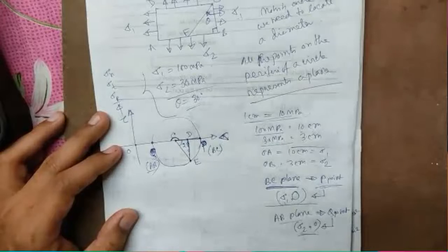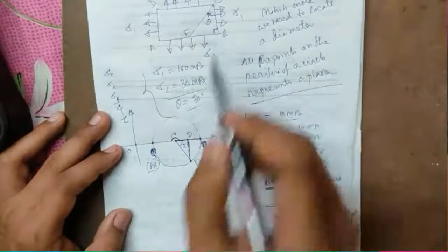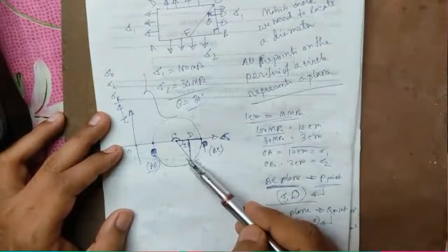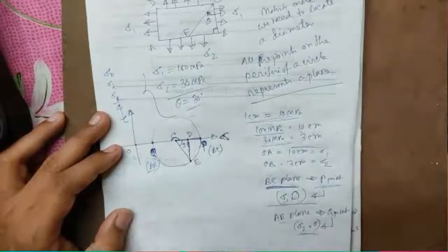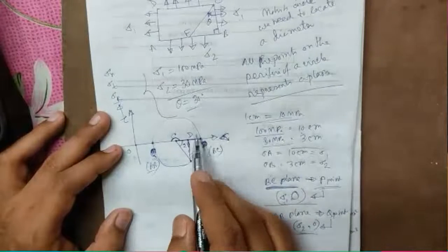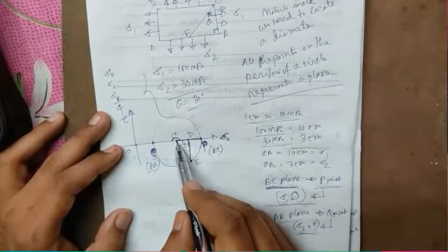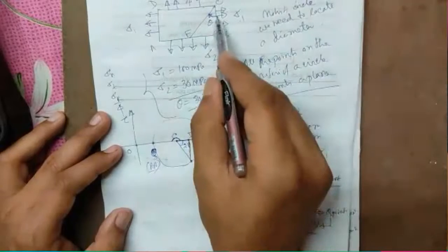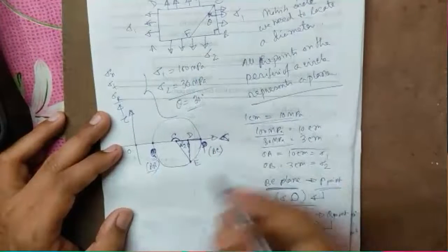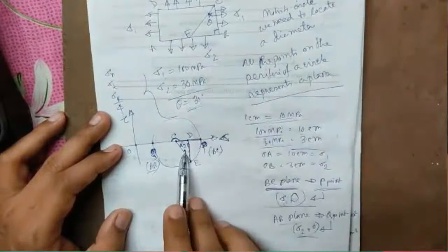Now here, P is actually BC and Q is actually AB, which are 90 degrees apart here, so they make 180 degrees here. That means all the angles here will be represented as double in this Mohr circle. So when we get 2 points on a diameter of that circle, we draw the circle. Now from that center, the theta angle in this diagram becomes 2 theta in the same direction. This was clockwise, this is also clockwise. Here the angle was theta, here the angle should be 2 theta.